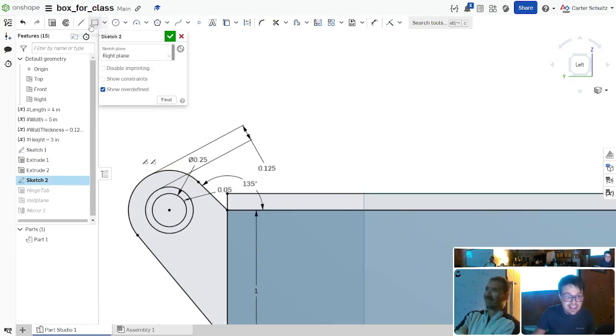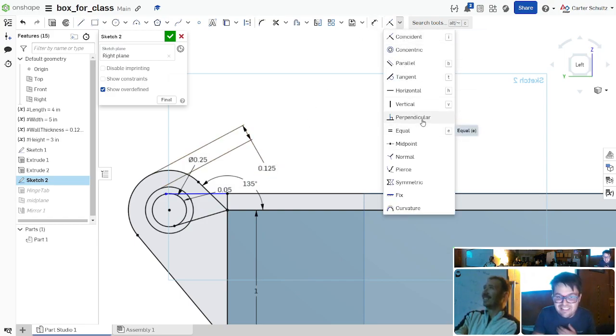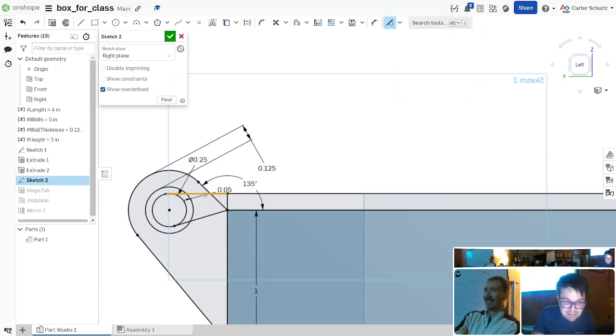And I'm going to do that however I feel like. What floats my boat today? We're going to do a line. Oh, this is going to look real funky. Oh, well, whatever. Some guy on Thingiverse will make fun of me later. Let's make this tangent to that. And there, that's fully constrained. Just 2 straight lines from the edge touching the circle there.